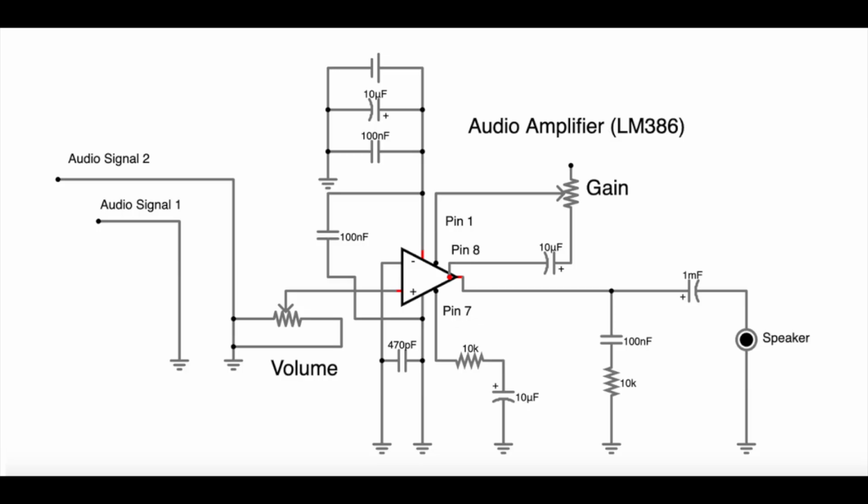This is the schematic of the amplifier. Since the headphone wire has 2 signals, one goes to ground and the other to the non-inverting input. The other headphone lead is connected to a potentiometer acting as a voltage divider. The more the potentiometer is turned, the louder the signal will be, as there is more voltage provided to the circuit.